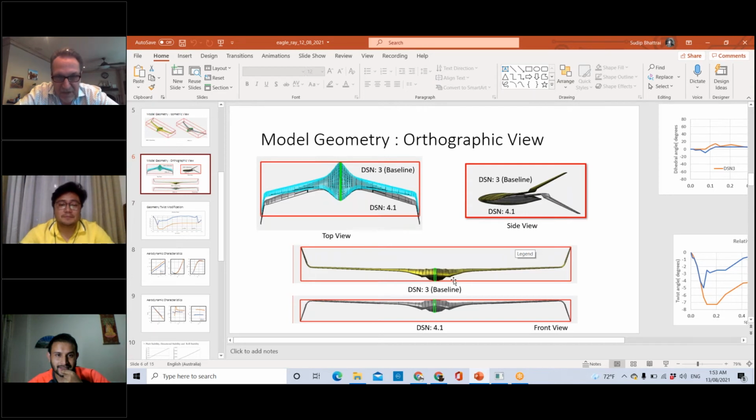So let's look. The intent ultimately is that those would be smoothed. And you've probably noticed if I have a lot of defining stations, I can move things. Sometimes I can move them a lot and I don't see a lot of change, right? If the slices are close together and I change one airfoil, obviously it's not affecting as much of the area, and then the three-dimensional effects cause it to relax the influence in any case.